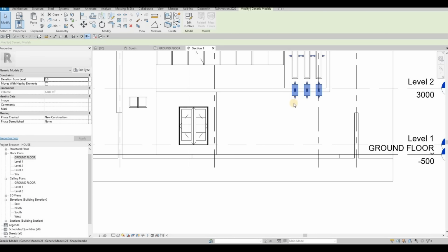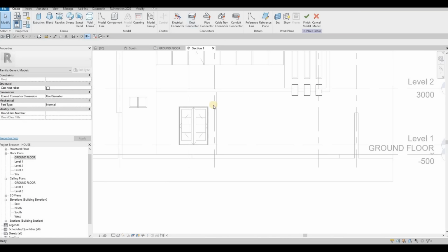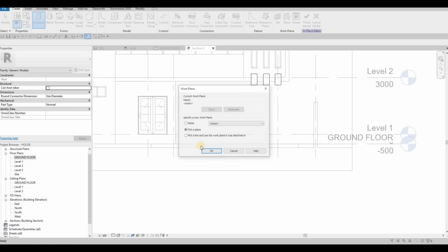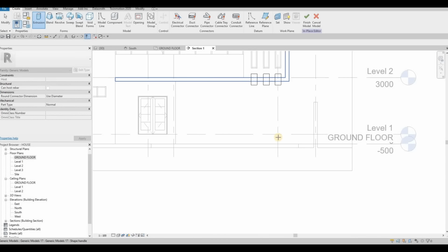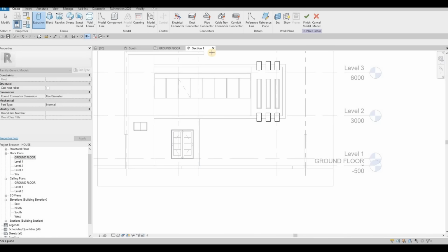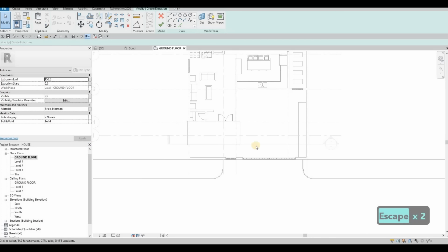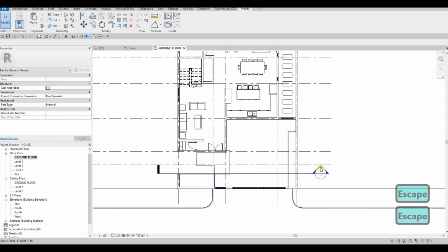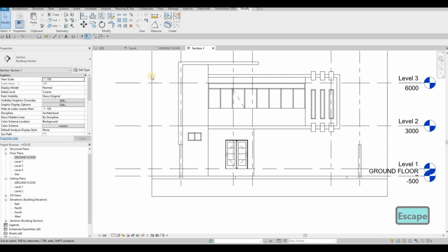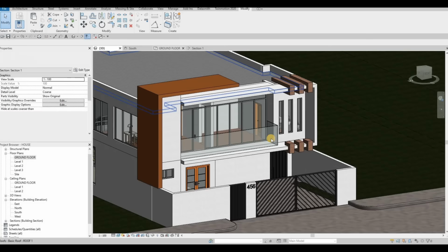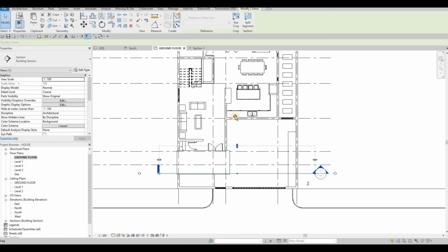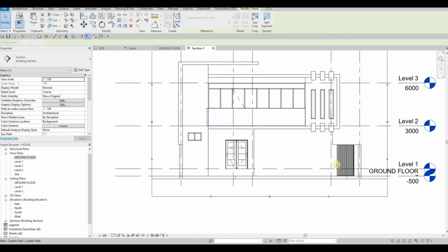And then also I want to add edit in place, extrusion first right here. Pick a plane, let's select, we need to do this later on in terms of the extrusion. So let's close this off first. Let's do the stairs one at a time. It's because I couldn't find the wall there. We need to push this one more so that it's visible in the section. So that's your viewport. So now we can select this.